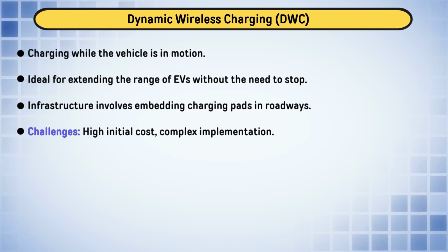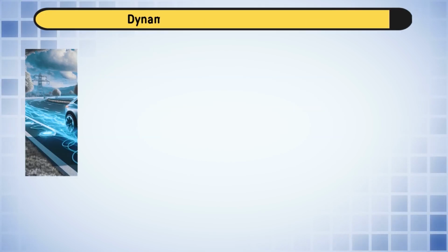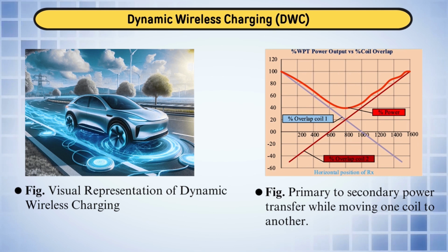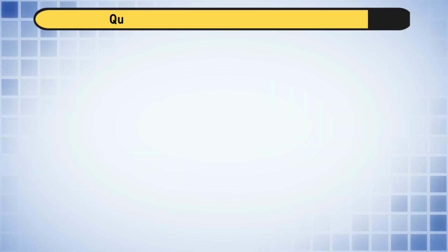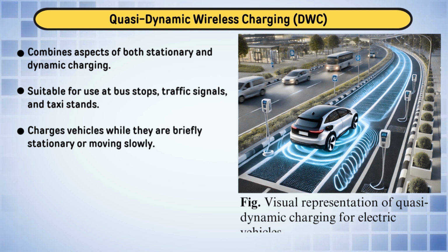As soon as you increase the switching frequency, the size of the transformer will reduce, as the size of the transformer or the value of inductance is inversely proportional to the switching frequency. So, in many applications people are going for a higher switching frequency, so that the size of the transformer can be reduced. And the operation is simple, as a converter which we have seen in the last slide.